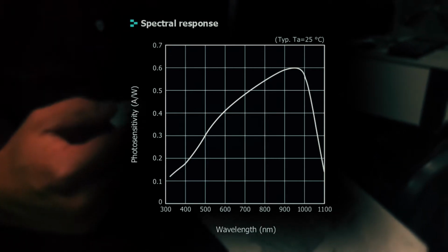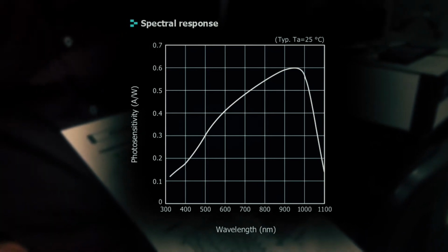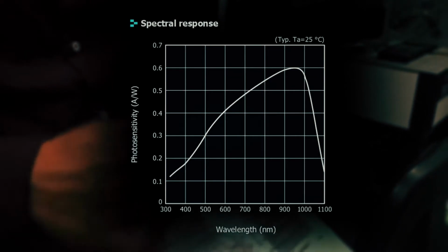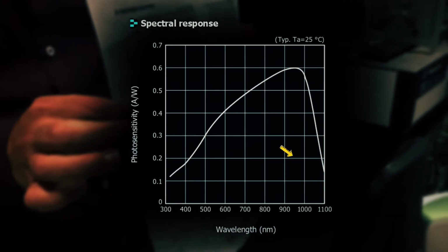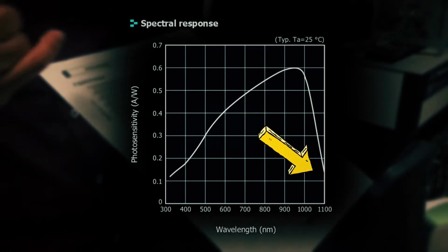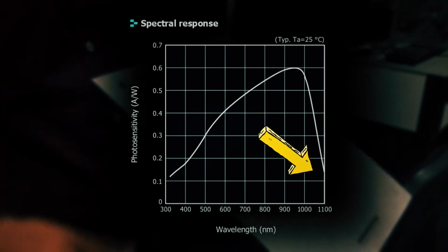Observing the expected response, it is possible to see that the response of a photodetector has an associated cut wavelength, corresponding to the energy below or the wavelength above the energy gap of the material. The device starts to respond at wavelengths lower than 1100 nanometers, since it's where the energy of the incident radiation starts to match the energy gap of the material, and so it starts absorbing energy.